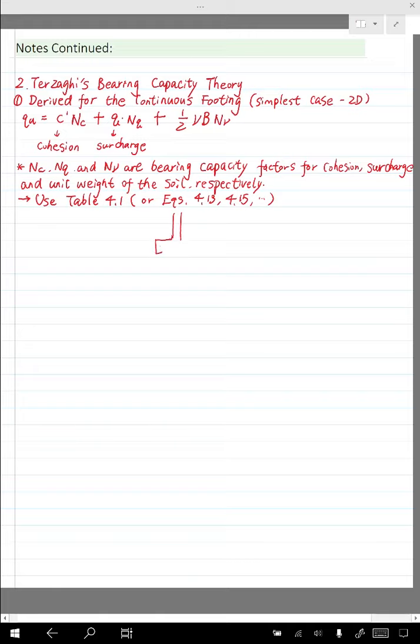And I will offer a little bit of theory relevant to the deduction of the bearing capacity equation. So ground surface is here. And here, this is B. That's the width. A critical surface that you need to keep in mind is the bottom of the spread footing. If a failure were to happen, usually it looks something like this. So a shear surface could be like this.